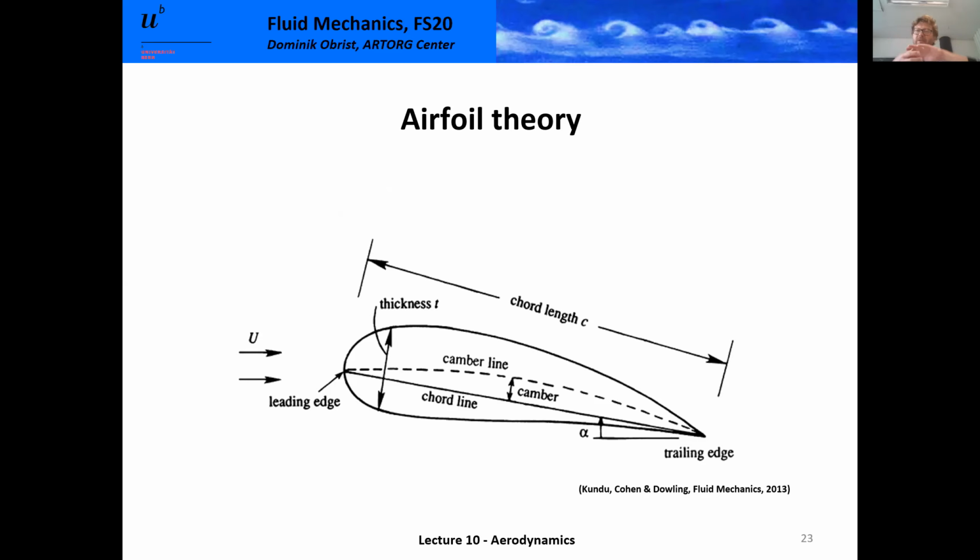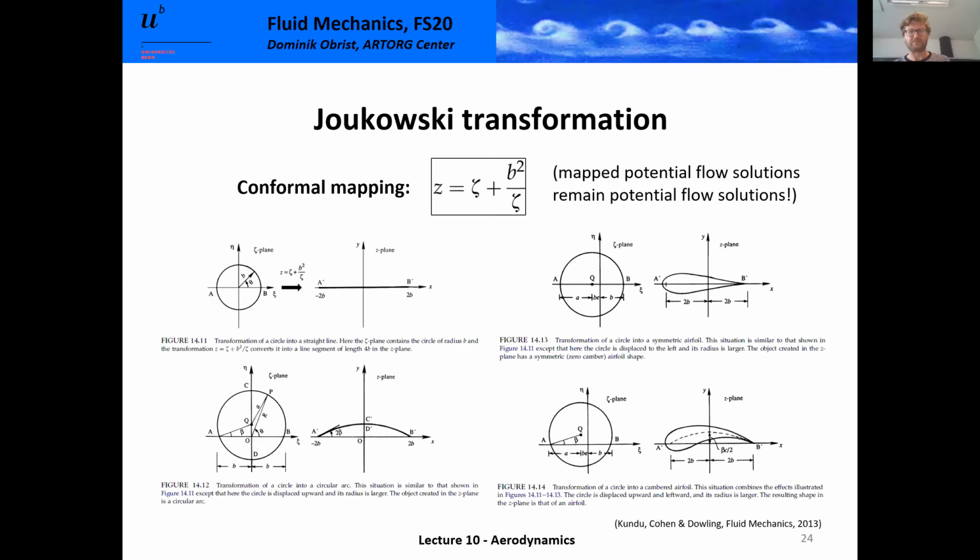And what they do is, well, they change the geometry, change the coordinate system, if you like, and they're conformal in the sense that they maintain the analytic properties of the solution. So if we take such a complex potential W of Z and we do a conformal mapping with it, the mapped solution is still a solution of the potential flow theory. Okay, maybe I should show you a picture to clarify that.